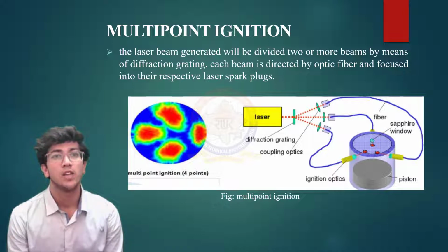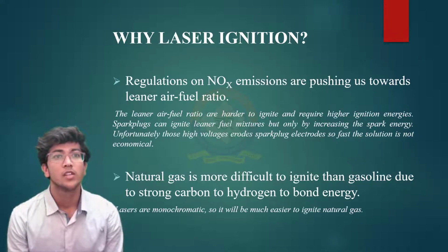The higher spark energy will increase the ignitivity but decrease the life of the spark plug due to electrode erosion. Therefore, to overcome this difficulty, multi-point laser-induced ignition is an innovative alternative approach to burn lean mixtures compared to the conventional electric discharge ignition system. Now let's study why we prefer laser ignition as compared to conventional spark plug.